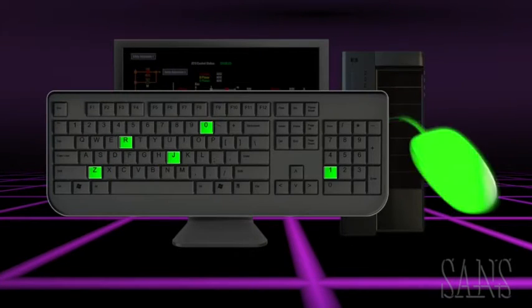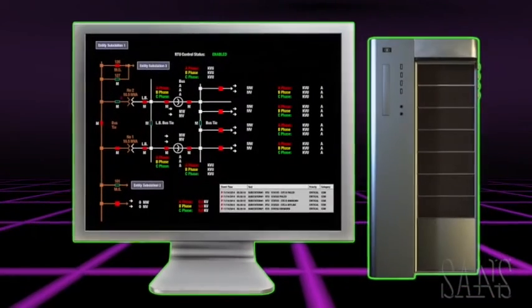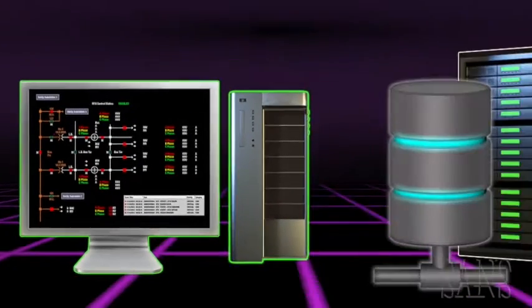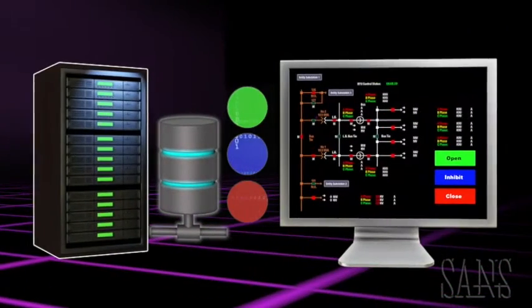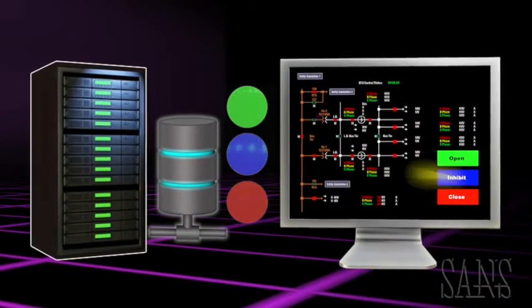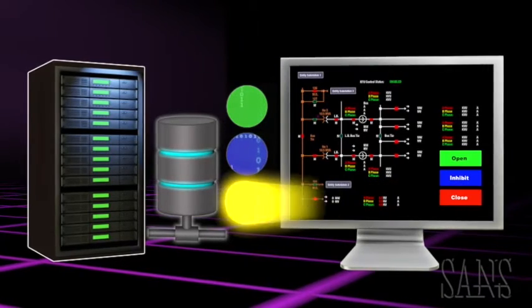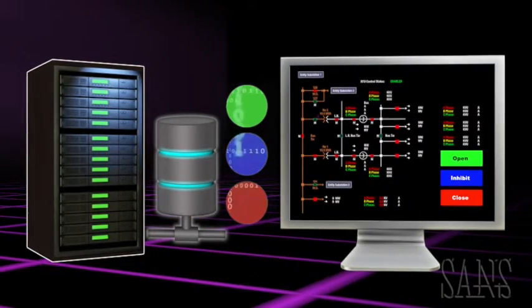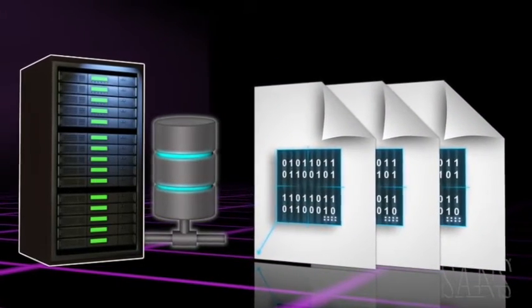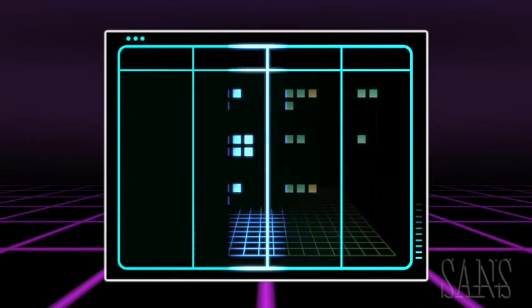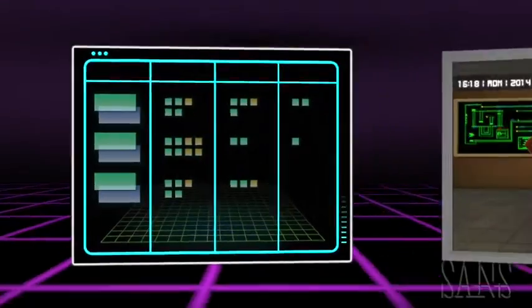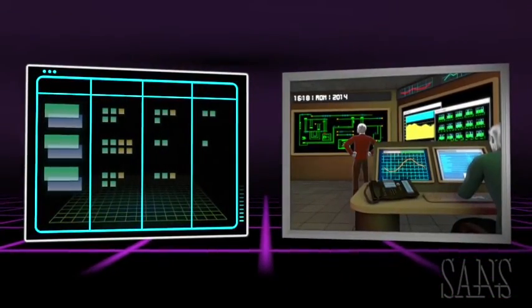When the keystroke or mouse action happens, it is sent to the EMS application, which then forwards this to the appropriate database. The database then maps the icons and buttons on the operator display to specific data points in the field. Think of these databases and configuration files as lookup tables and a detailed list of actions to take when a particular event is seen.